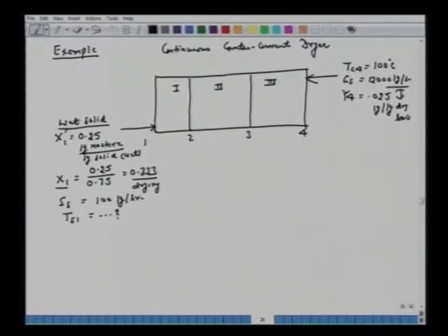And it says that this solid has to be dried to the temperature Ts4 of 60 degrees centigrade, and the moisture content x4 prime, wet basis, is 1%. So quickly we can calculate here x4 as 0.0101. All right. So the solid has to be dried from 0.333 to 0.0101. The flow rate of the solid is given, the flow rate of air is given, the moisture content Y4 is given here and the temperature here is given.